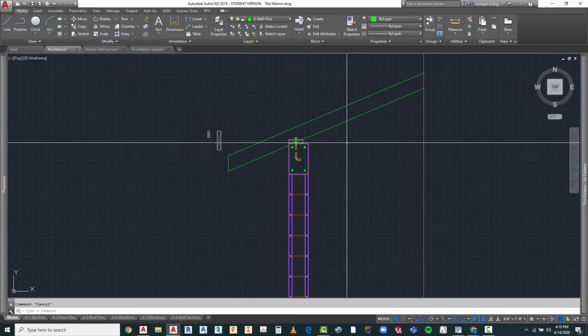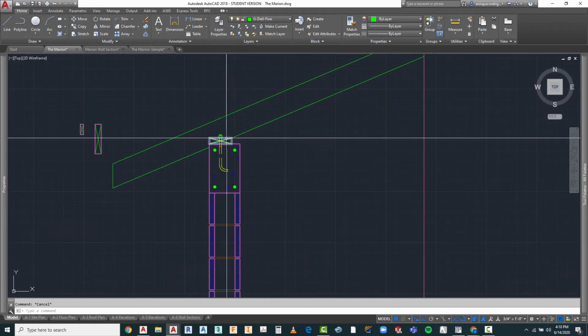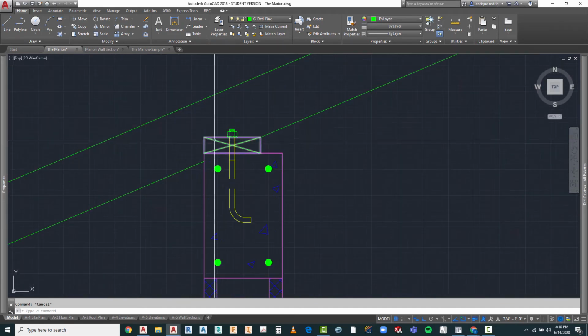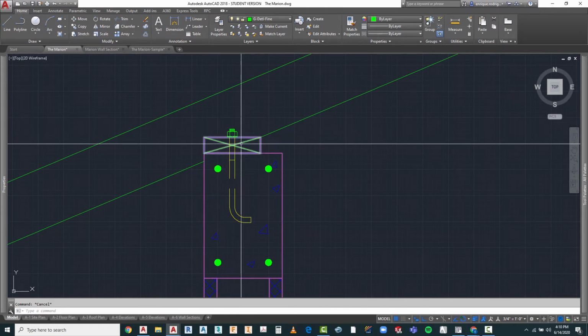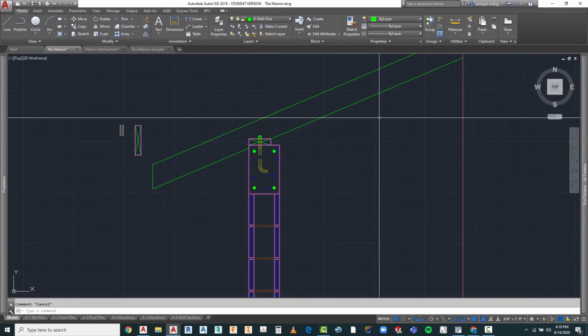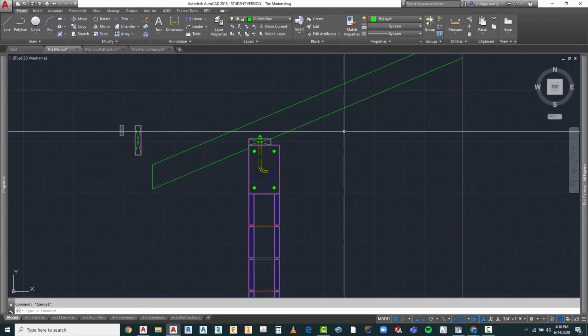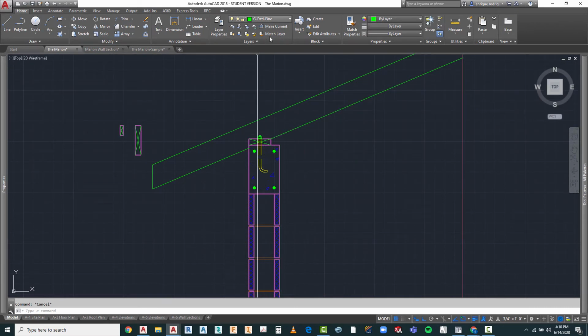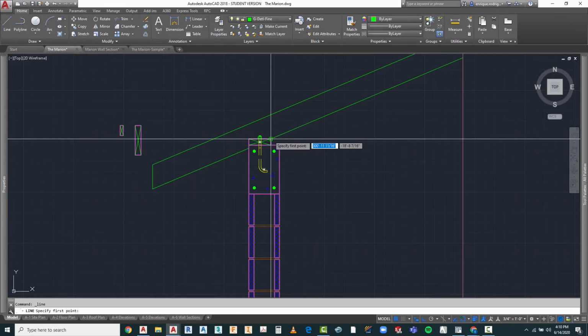The next element we're going to show is going to be our ceiling joists. Our ceiling joists also rest directly on this top plate. They're going to be directly horizontal. If we wanted a vaulted ceiling, we wouldn't have these. But I'm going to go ahead and use G-Detail Fine also for the ceiling joists. And usually they are located,